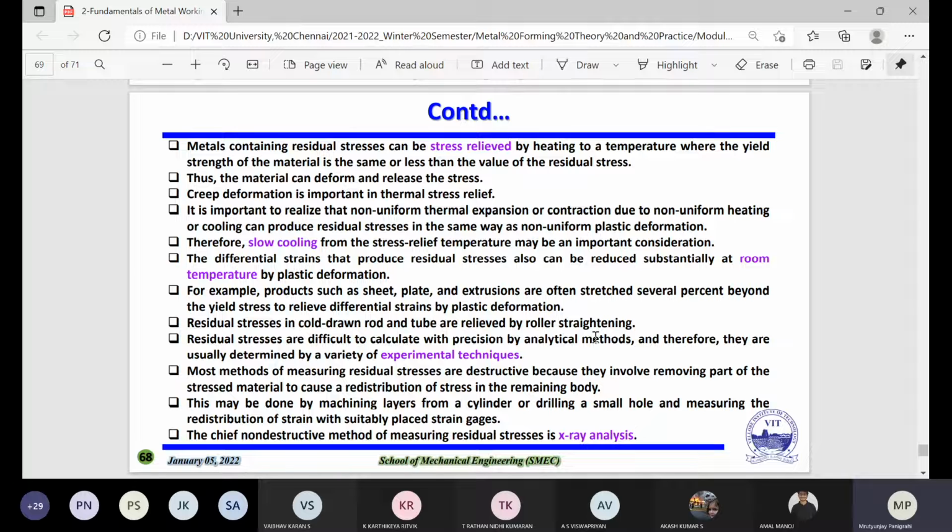you also have to hold at that particular temperature. Let's say if you are maintaining 300 degrees, you have to maintain it, because sometimes in the furnace the temperature is fluctuating. The moment it is fluctuating, that is also one effect. Maybe you can get some cracks there, or maybe you cannot get the growth properly there.